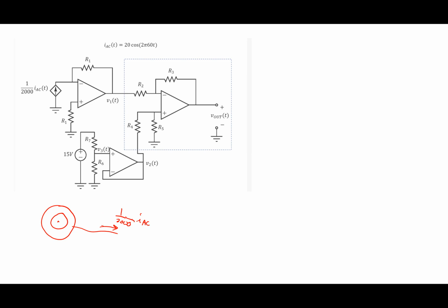If I had a control system, a microcontroller, and I want this microcontroller controlling something, I would have to get that. If I use the example of a PV system, a solar system, I need to control that current. I want that current to look a particular way. If I make a PV inverter, it is trying to be a current source. And so I'm trying to make the current look like whatever that is. So to do that, I got to measure it.